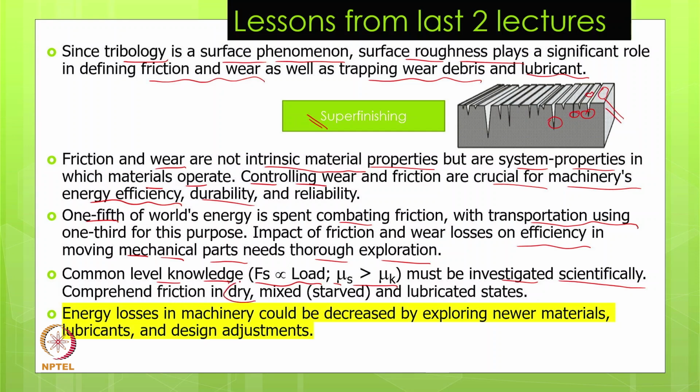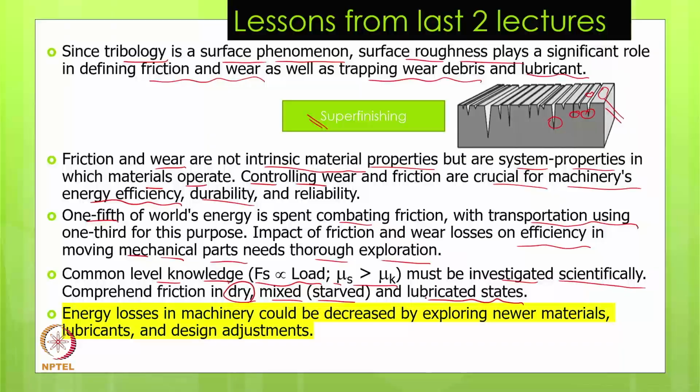Most of the theories we cover are related to dry friction, but we want to cover also mixed lubrication, sometimes called starved lubrication, and completely lubricated states. So friction in the dry case will be different, friction in mixed lubrication will be different, and friction in the well lubricated state will be different.